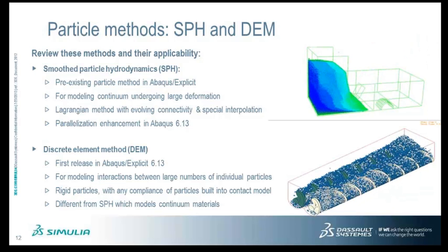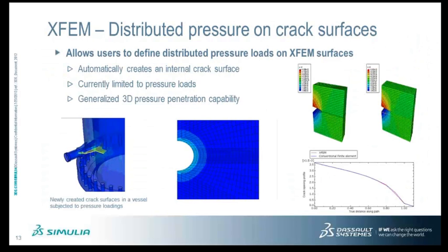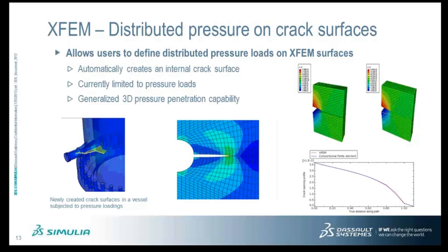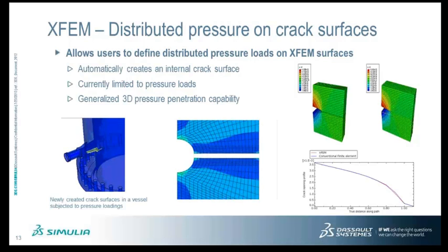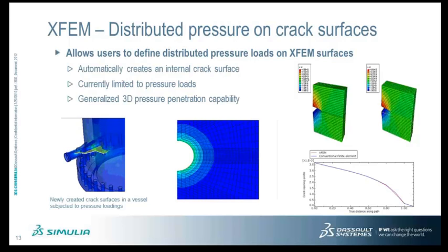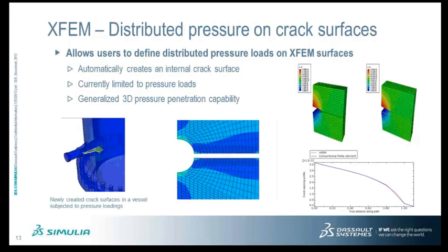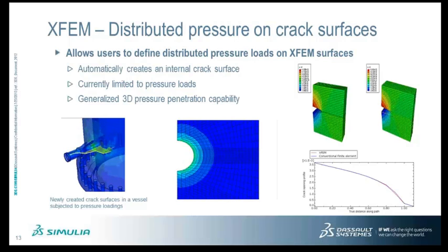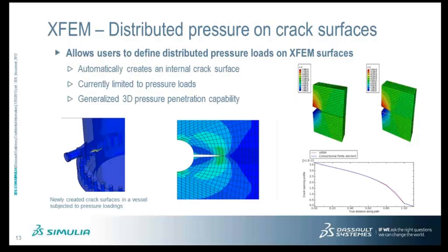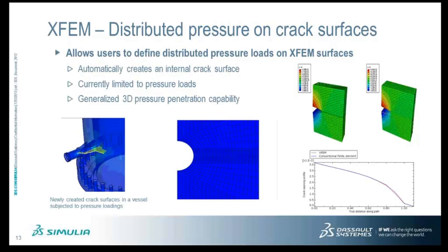Okay, so on the next slide, I want to talk about XFEM. So XFEM is our extended finite element method. We've had XFEM in Abaqus Standard now for 4 or 5 releases, and we continue to enhance it. In 613, one of the major enhancements was the ability now to apply distributed pressure loads on the surface of an XFEM crack.